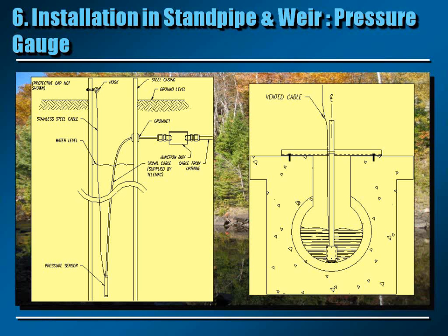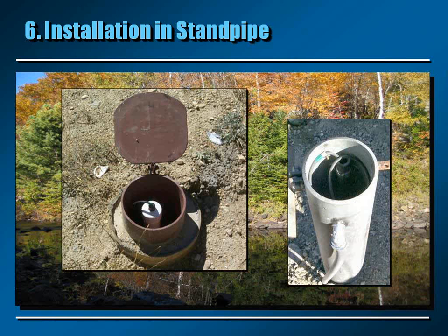Low-range piezometers can also be installed in a weir or small reservoir, as shown at the right. You may note that a vented cable is required in that case. Okay, these pictures show the installation in a standpipe.